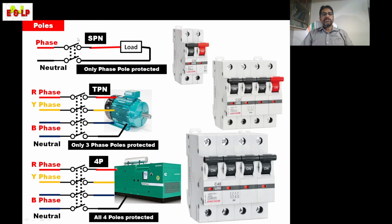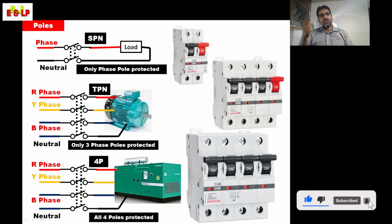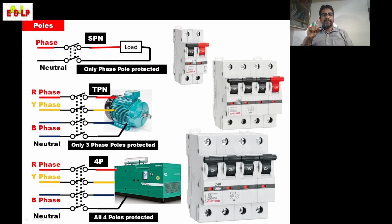Next is SPN, single pole neutral, means only the phase pole will have protection, but neutral will not have protection. But when it is breaking, it is linked. Both the poles are linked, so it will operate together, but the protection is only for the phase pole.